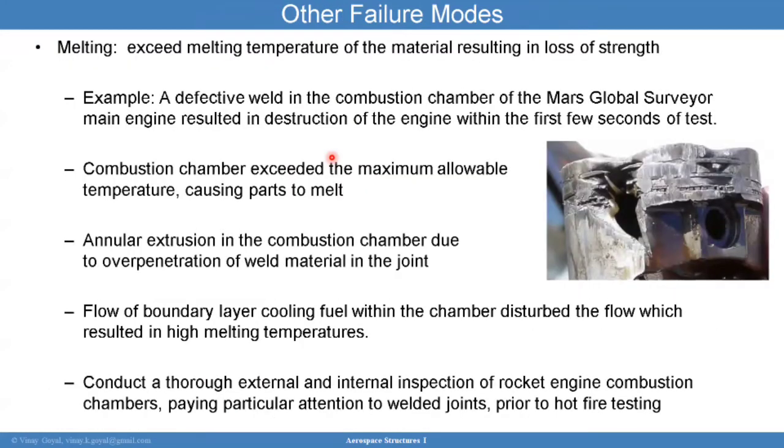We also have examples of melting where the melting temperature of the material had been exceeded, and so it resulted in loss of strength. An example of this application is the defective weld in a combustion chamber of the Mars Global Surveyor main engine, which resulted in destruction of the engine within the first few seconds of test. The combustion chamber exceeded the maximum allowable temperature, causing parts to melt.